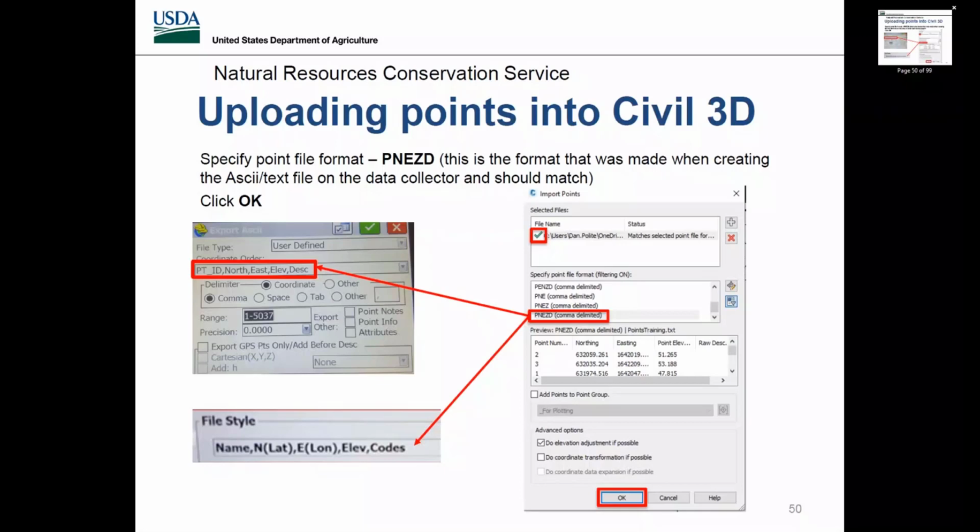Hey, Dan, I used it on one of the designs that I was doing recently off LiDAR, and it just made everything super wonky. I had to add some culvert pipe shots just so I knew exactly where I was at, and it just changed everything. And that's when you had it selected then? Yes, and then I went back and unselected it and did it again, and everything stayed as it was. But you're saying LiDAR, because LiDAR is a whole different thing. You're bringing in a DEM file. So you were putting points over top of the LiDAR, I gotcha. I see, just for reference points.